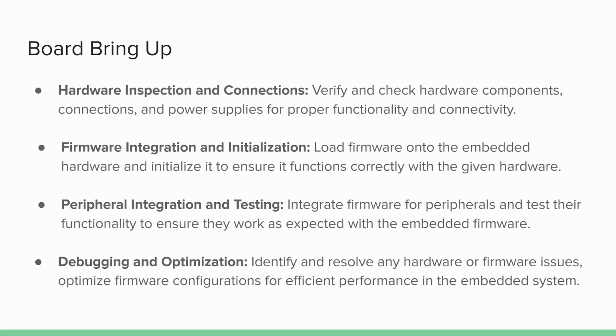You also need to build a debugging setup, so make sure you are able to debug your code. It could be using a debugger such as JTAG, or just printing logs on the console. So you should have a connection with your PC. ESP32 boards all usually have a USB connector which can be used for debugging as well.